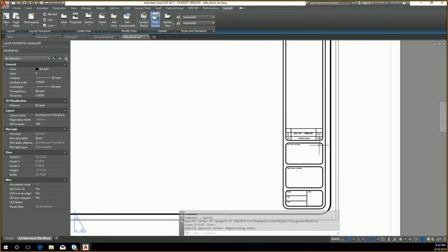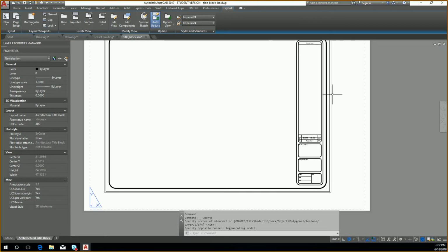So within sheet 1 all the way through 10 of that one package, your revisions need to be consistent all the way through. So within AutoCAD right now, the way it's set up on the version that we're using, you would manually go through and edit that one by one. So very important that you keep track of changes like that, but be aware of what a revision system is. Are there any questions about how revisions work or what they really are?